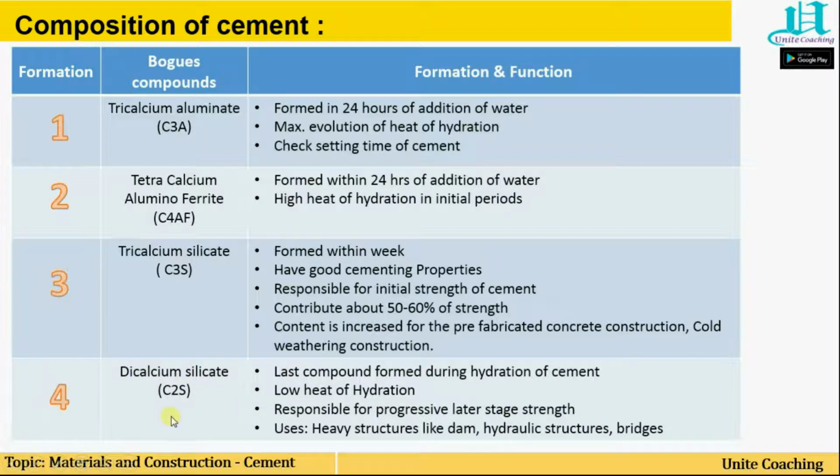So in which cases can you increase the dicalcium silicate percentage? Heavy constructions like dams, hydraulic structures, bridges. In short, those structures in which mass concreting is done, in that case you can increase the percentage of dicalcium silicate.